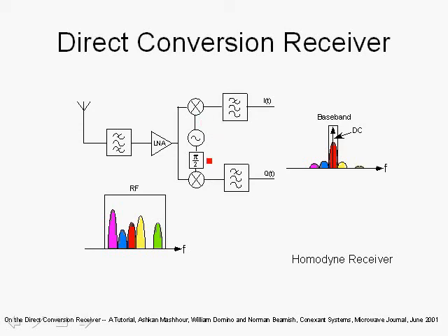You can also have, even more detrimental, a phase mismatch between the in-phase and quadrature phase modulator, or in this case used to demodulate. And we'll get into that and see what the effect of both the gain mismatch and the phase mismatch is on the IQ imbalance.